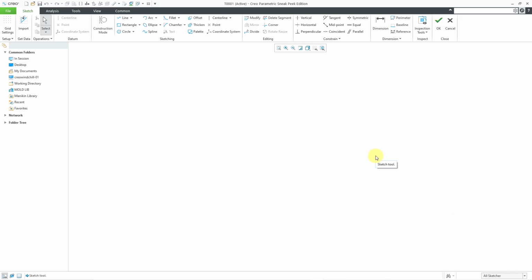This takes me into sketch mode, and it's sort of like a slightly degraded mode of sketching compared to what you are used to. One of the requirements for the sketch is that you have to have a vertical center line for an axis of revolution. Let me go to the center line command. By the way, you will notice that the center line command in the data group is grayed out. We only have access to the center line command from the sketching group. But anyhow, I will click left to start it, make it vertical, and then click left again.